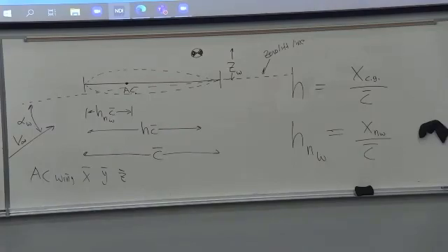And the reason we define this zero lift line is that CL of the wing is the lift curve slope of the wing times that angle. Right, because if that angle is 0, we don't get any lift, so then it's just the slope times that angle. So are we good so far? Again, we're just defining dimensions and angles and locations.